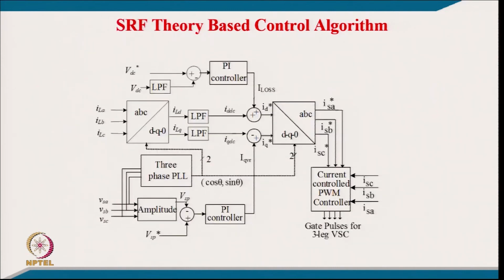Well, we have another control algorithm which is a very famous algorithm, the synchronous reference frame theory based control algorithm. This is DQ theory, which is used in electrical machines analysis as well as in vector control of the motor drive, AC motor drive. This is the same algorithm which was first used by the Wisconsin group, and it is reported widely and used for a lot of systems, including not only D STATCOM but also active filters as well as solar inverters. So, plenty of places these are used.